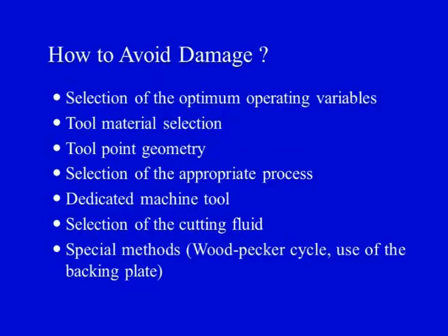Then we can think of a dedicated machine tool, because the nature of drilling or machining of polymer composites is entirely different from the machining of metals. Therefore, the machines that are used for machining of metals should not be blindly used for machining of polymer composites.